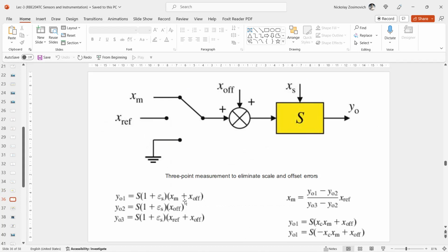Dynamic correction involves a particular sensor design. Basically, the method involves a series of measurements of the same quantity in such a way as to eliminate the errors by post-processing. And this can be done in various ways, according to the type of quantity and error. First is multiple input signal measurements, to eliminate scale and offset error. Second, cycling, interchanging of components, or dynamic matching. And third, cycling, changing the sensitivity direction of the sensor, or flipping.